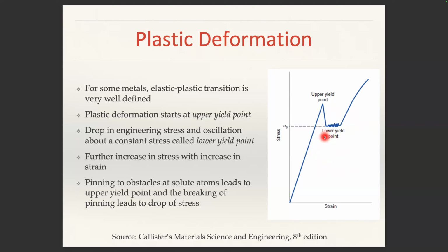You can see that the atom size of carbon is much smaller than iron. And what happens is, these dislocations are encountering these solute atoms called carbon, a very small percentage. Whenever they encounter one, they see some resistance, but then dislocations are strong enough to overcome the obstacles. When it overcomes, the stress required drops. Again, it will encounter another solute atom. Like that, all these solute atoms are causing these oscillations. And once there are enough dislocations, your grain boundaries start offering resistance to dislocation motion, and hence you will have this strain hardening, or work hardening, taking place.